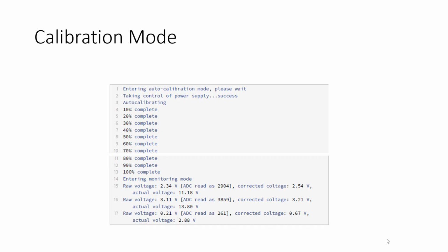Remember, I don't know if you guys use power supplies in electrical 201, but power supplies normally are designed for you to set the output voltage and current before you enable them. Typically you're not changing the voltage while they're enabled. That's weird, right? But we are in this lab. You don't normally do that. Normally, you set them up ahead of time.